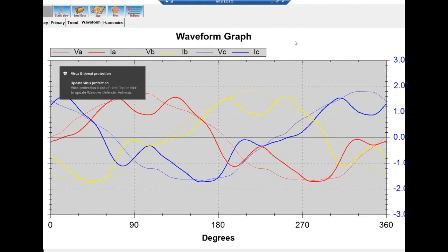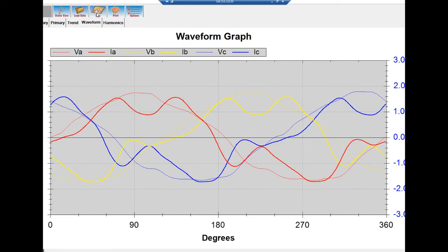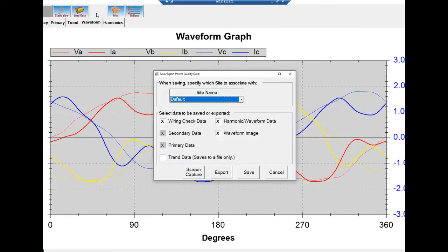So to do that, if I wanted to save all this, I can choose to save this specific data. So if I want to save this harmonic content off, I want to create a file from it. I want to be able to create what we call the COE file, which is a coefficient file that we use to then tell the equipment what harmonic order, magnitude, and phase, just like what we were seeing in the harmonic tab, and use that to generate what we just saw at the site.